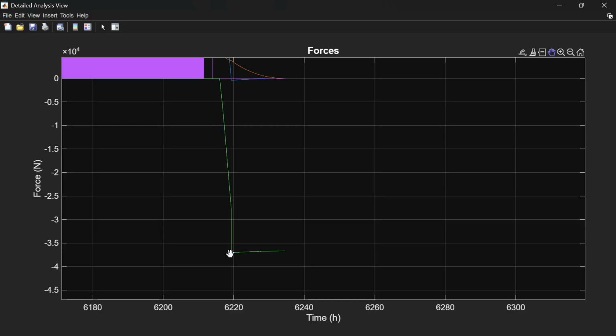Here we have the maximum value, and it becomes a slightly lesser value. The reason is I'm deflecting my elevator to its maximum value, negative side of course, which creates a downward lifting force that enhances my normal force. And as you can see, as I further slow down and decrease my velocity, the effectiveness of the elevator decreases, and that contribution slowly becomes negligible, or let's say 0. And here is the effect on the normal force.